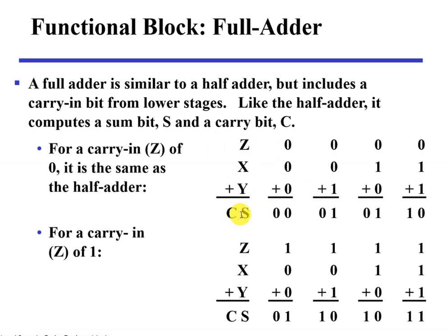Again, the 2 outputs are designated by the symbol S for sum and C for carry, as we have introduced in the half adder example. The binary variable S gives the value of the bit of the sum, and the binary variable C gives the output carry. Output carry, and this is the input carry, carry in. So we have the S as a result of summation.